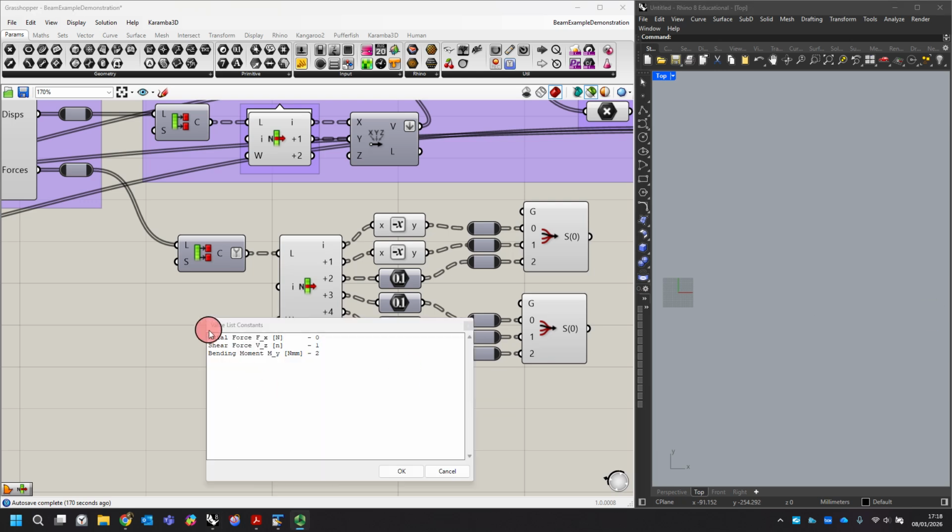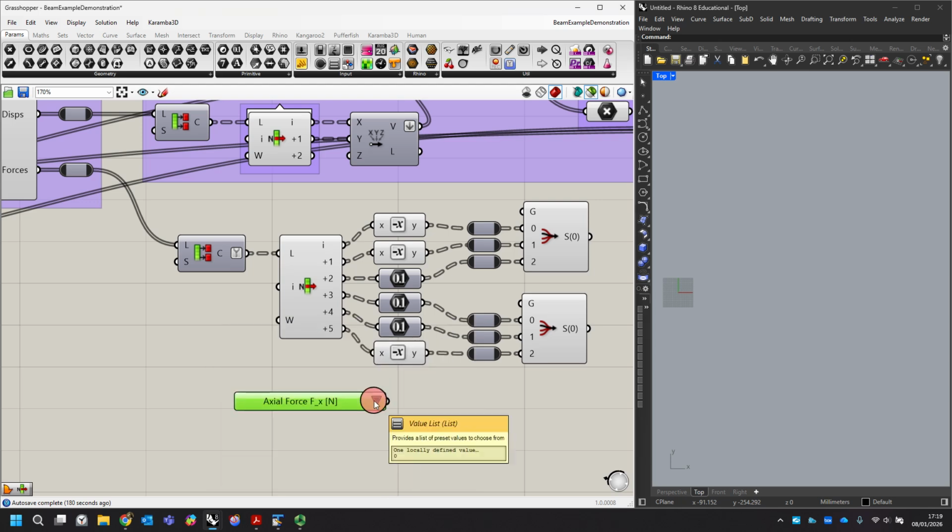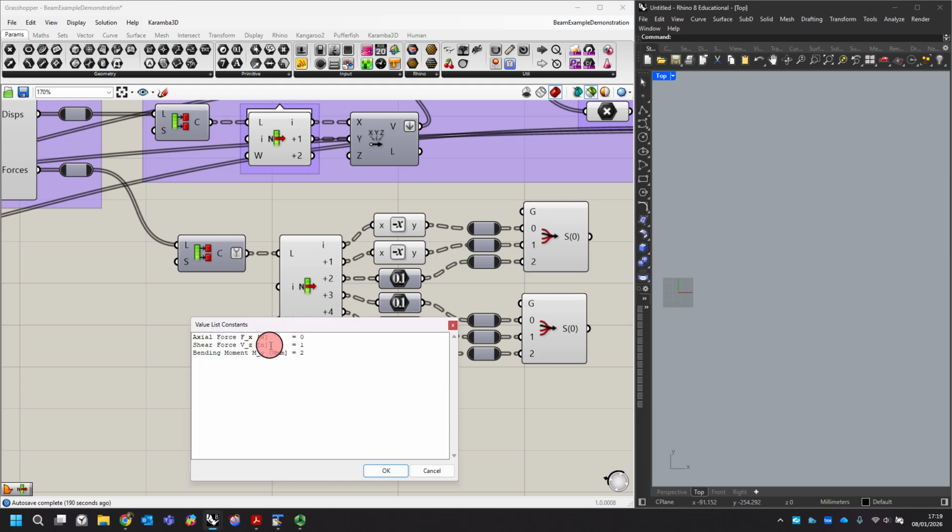Okay, so I just needed to edit how I was writing that. So this should be equal to those values. And let's just see, yeah. So now if I go through, it will let me select the shear force, the axial force, or the bending moment. I'll just go in and correct that unit on the shear force.